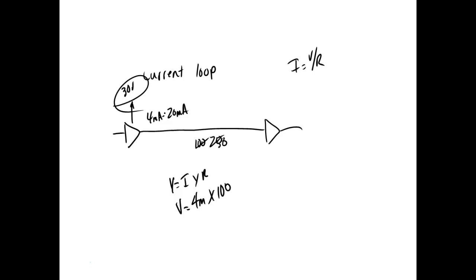So you're going to run into current loops a lot. When you get out in these big noisy industrial environments, you're going to run into EMI a lot, and current loops a lot, especially in older plants. Why? Number one, they're almost immune to the length of the wire, right? And another thing is they're basically immune to EMI. Now we're seeing a resurgence.